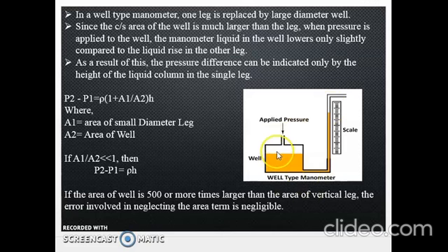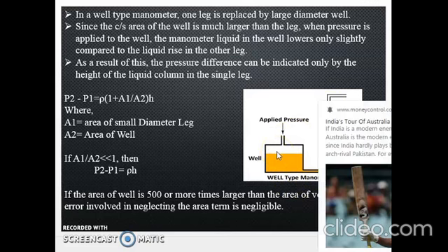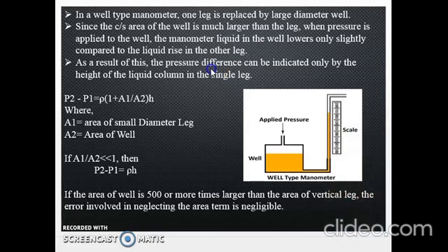So by using the well type manometer, we can achieve the amplification principle by using a large quantity of the manometric liquid.